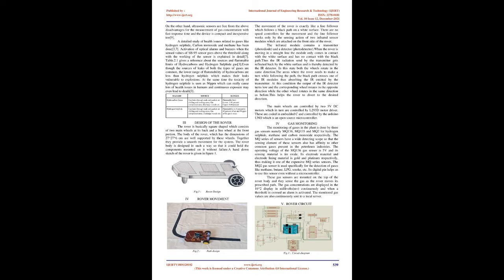Even though the sources of leaks of both types of gases are common, the lower range of flammability of hydrocarbons is less than that of hydrogen sulfide, which makes their leaks vulnerable to explosions. At the same time, the toxicity of hydrogen sulfide is seen at 50 ppm, which can cause many health issues in humans, and continuous exposure may even lead to death.